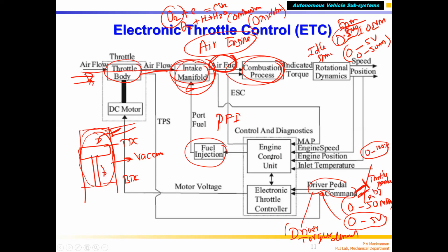Then of course compression happens, gives spark, and then combustion happens, and power stroke. Further combustion continues till the power stroke, and finally when it comes down, the piston comes up again, which is called the exhaust stroke. The exhaust valve opens, the burnt fuel just goes out, correct?